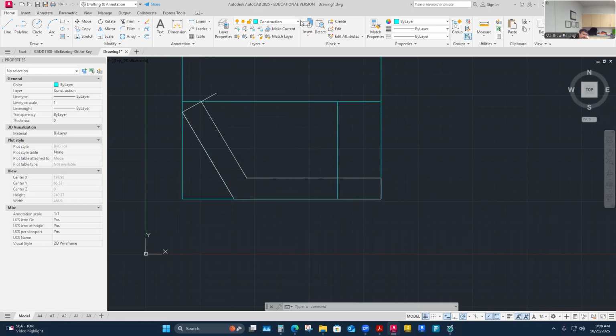So I think I'll just draw those in as visible, based off that center line, right? So it goes over here. Maybe I'm just going to cursor over so I don't do a bunch of visible line over the top of visible lines. 32 and a half, 65 divided by 2. So I'm wanting to turn that diameter into a radius in my head.